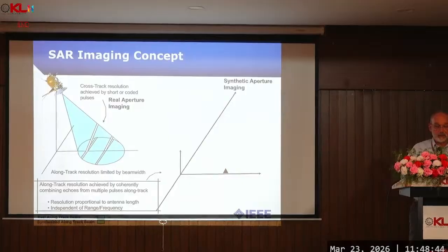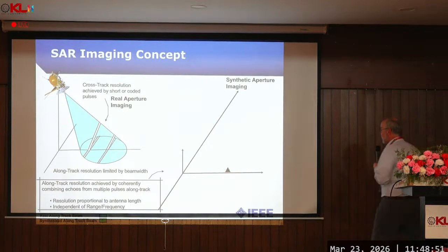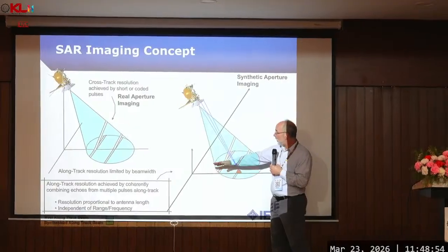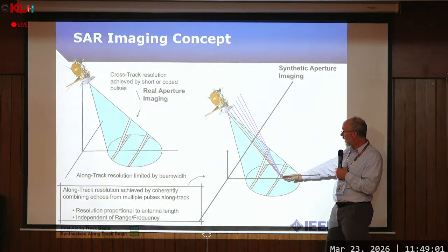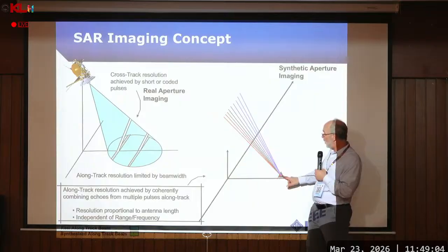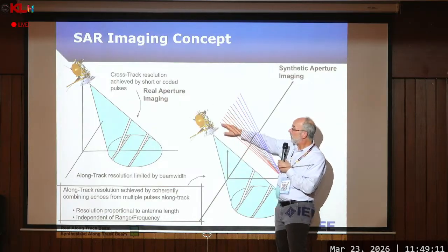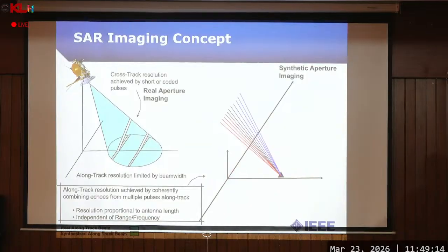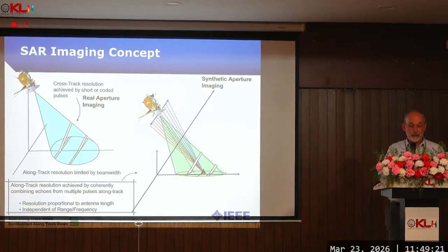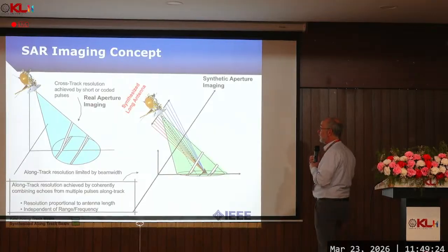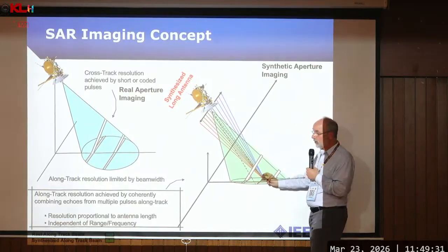So for SAR imaging, we're flying along, as you can see here, and at some point we encounter a point target. It's before we get to the broadside direction, so you have a blue shifted signal coming in here, and as you fly away from that target, it becomes red shifted. So over the time that this point on the ground is illuminated, you get frequency diversity in the observation over that period of time. So using that frequency diversity, you can just imagine taking a Fourier transform. That's like a synthetic aperture, a synthesized long antenna, many kilometers in length, that allows you to build up resolution also in the azimuth dimension.